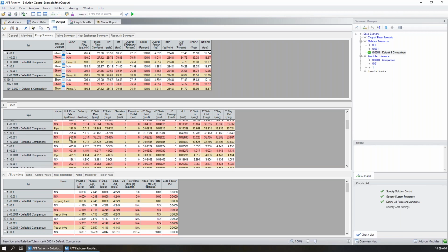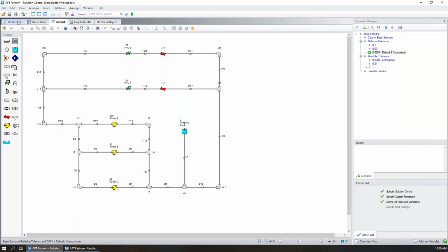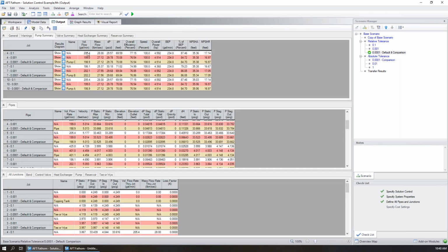So here we can see 0.1, we have a bigger flow rate change in pressure. So by changing tolerance, you can change the results. And with bigger flow rates, it's going to amplify that difference so much so it may impact your engineering design, especially here with pumps where we're looking at 3 pumps in parallel. Generally, you would hope to see the same head rise and therefore the same flow rate through each pump. With our very loose tolerance, we see 2 are carrying the 3rd pump, whereas with tighter tolerances, they're much closer to running at the same operating point.